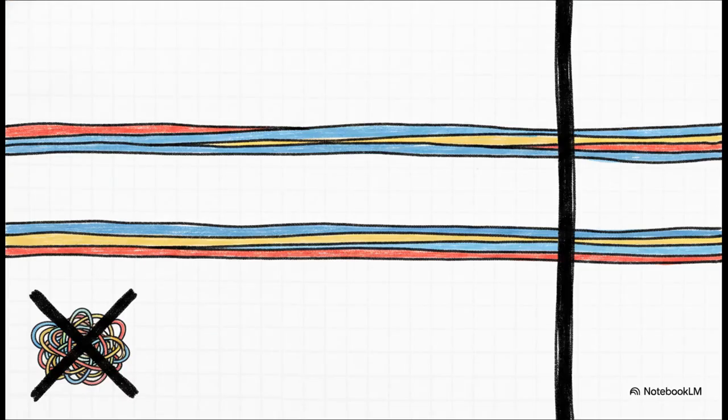Believe it or not, the cable-to-cable coupling inside your internal harness is often a way more chaotic EMI environment than any external interference coming from the outside world. You absolutely need a structured approach here. Cables must be physically segregated by their classification. We usually use categories like S1, S2, and S3 based on their sensitivity ranges.